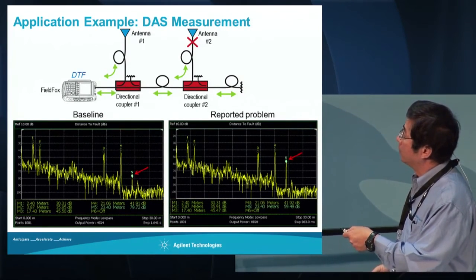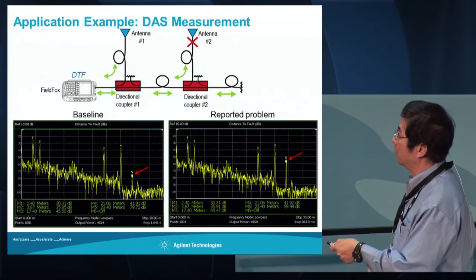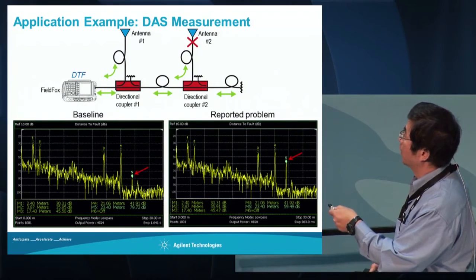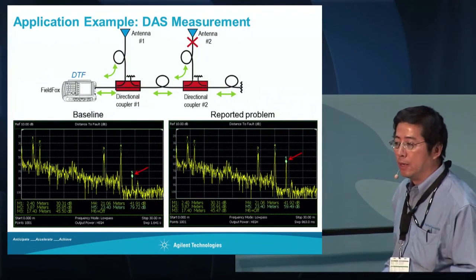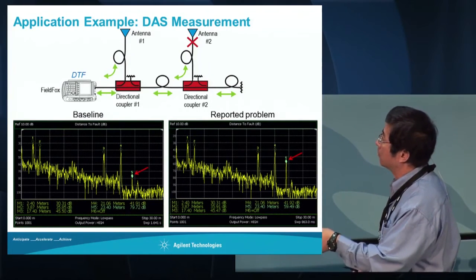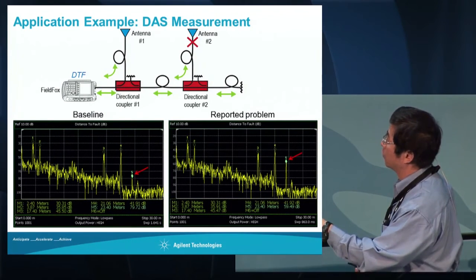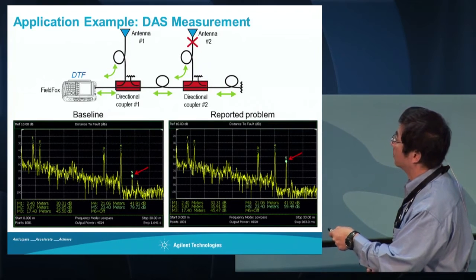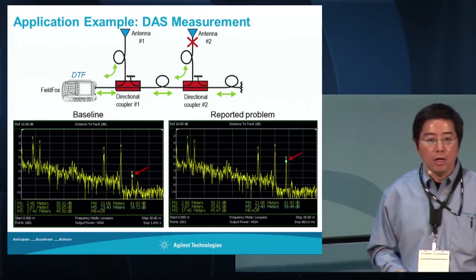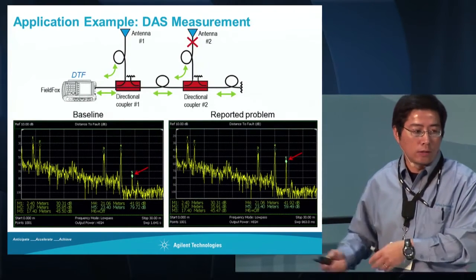We basically take 2 couplers and hook up 2 antennas. You can easily see each one. We can actually simulate whether we leave this one open or connected. So this one, if we disconnect, you see the signal going up. And that helps the user quickly identify which part is the problem. For example, over here, you can easily see this is the antenna, this is the adapter, before this is the coupler, then the second one, etc. Basically, you've got 1, 2, 3, 4, 5. Of course, in a real situation, it's much more complicated than that. You just have to test one section at a time.